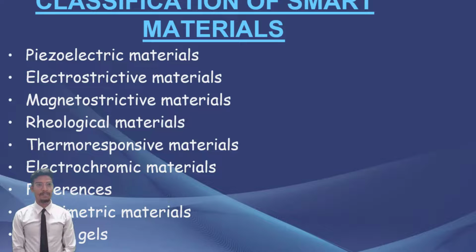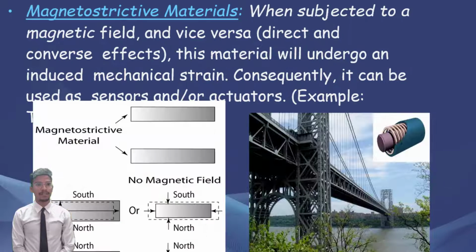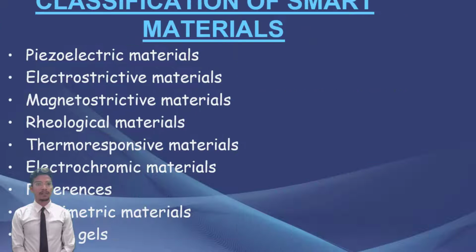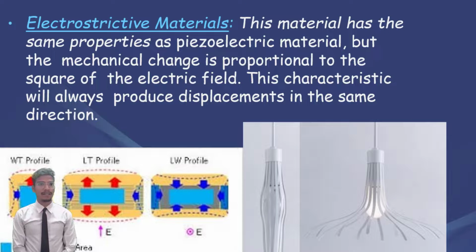And the next one is shape memory alloys and shape memory polymers, which are materials in which large deformation can be induced and recovered through temperature changes or stress changes. The shape memory effect results due to the martensitic phase change and induced elasticity at higher temperatures. Third one is photovoltaic materials or optoelectronics, which convert light to electric current. Electroactive polymers change their volume by voltage or electric fields.